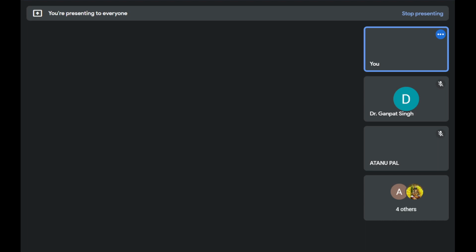What we know is the total input is 1.5 some units, and you need to know the total output. So we have two different outputs. One is the recycled matter and the other is the mixed waste, right? So we need to subtract them both. 1.25 is the recycled one and 0.1725 is the mixed waste. This sum is your total output. So we need to subtract your total output from your total input. That turns out to be 0.0775. Okay, so that is your change in storage, which is what is asked. Okay, is that clear?